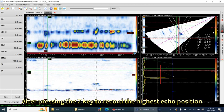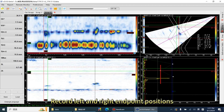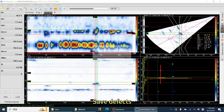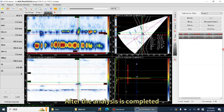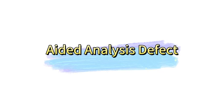After pressing the Z key to record the highest echo position, look for the left and right endpoints and record their positions. After pressing the C key to return to the highest wave position, save defects. Defect measurement completed. After the analysis is completed, click Defect Report. You can view all group defects.